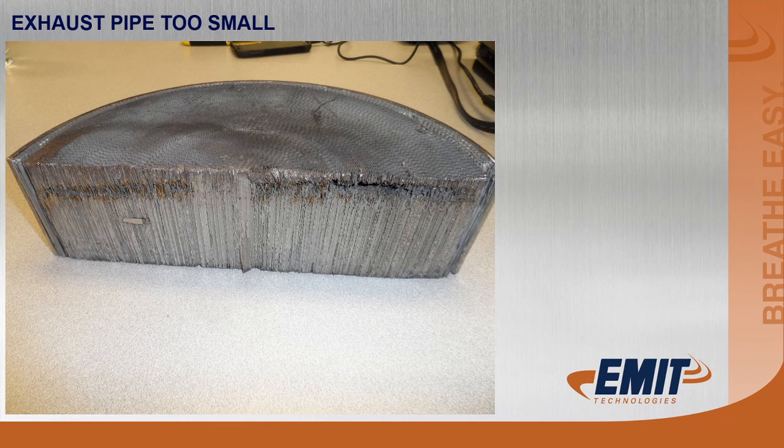Now this one, you can tell by the surface that the exhaust gases were not hot. They didn't have a big load on this. But the raw fuel was coming in here and burning. And you can see that it starts to react to the precious metals right in here. Okay? And when it reacts to those precious metals, it starts to oxidize, basically burn. And because the temperature was low, the surface was protected. Looking at this catalyst on each side, it was less than an hour old, and I had put the catalyst in, and still it had failed in a short amount of time.